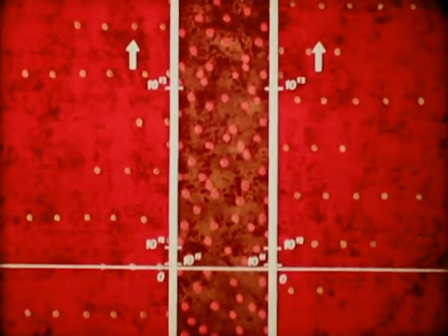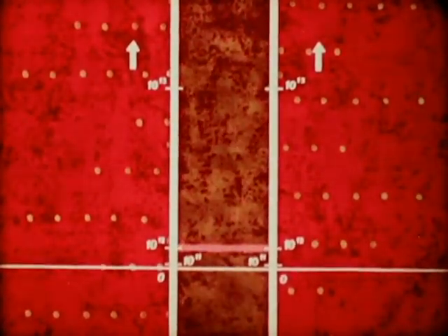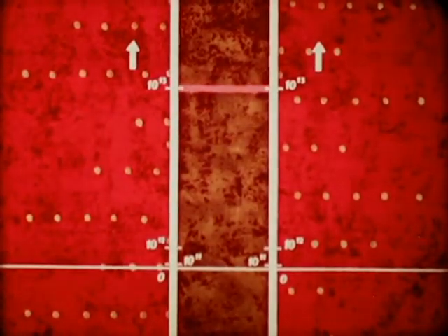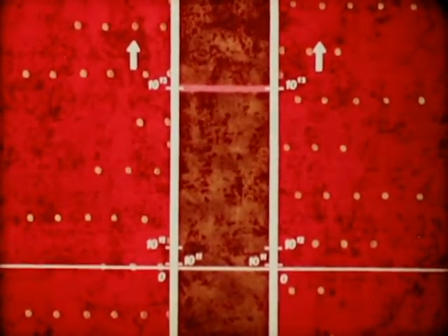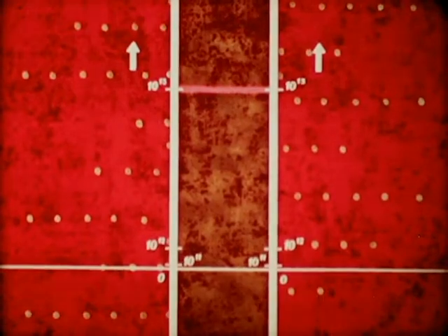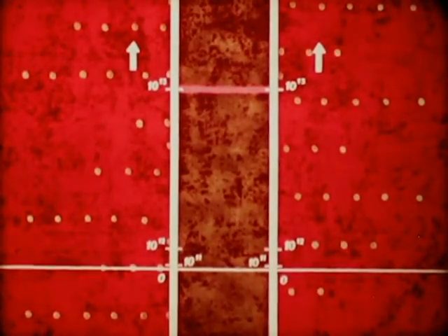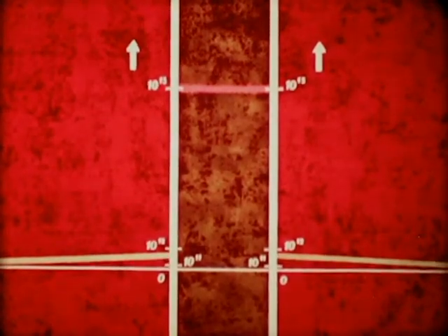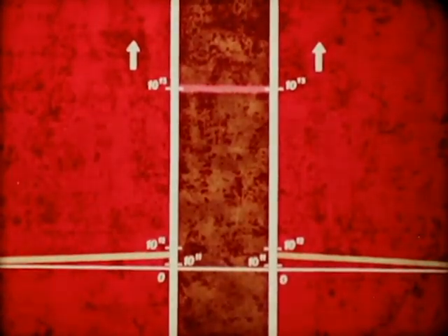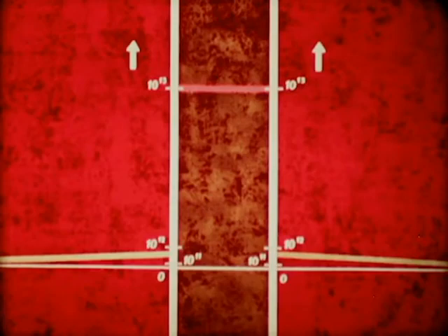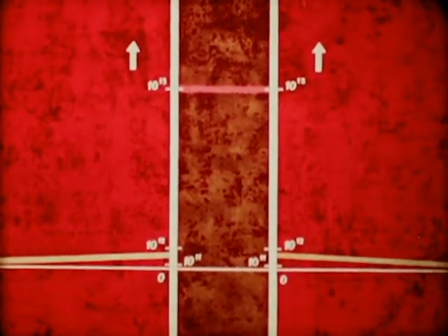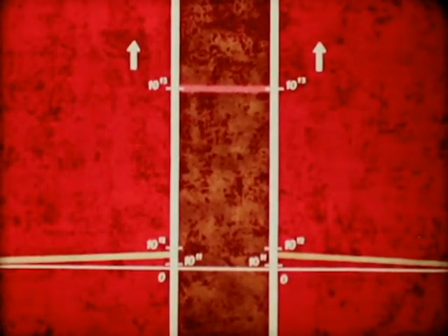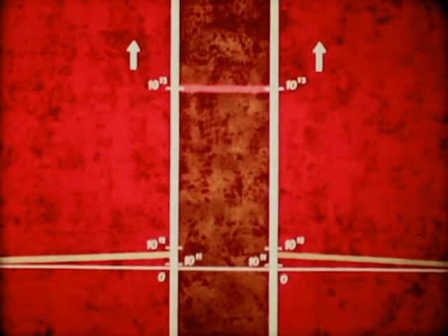Consequently, the concentration of holes in the base will increase considerably, and the electron concentrations in the emitter and the collector will, near the barriers, also increase. When the values of the two voltages applied are almost the same, the concentration graph of the holes in the base will be almost horizontal.